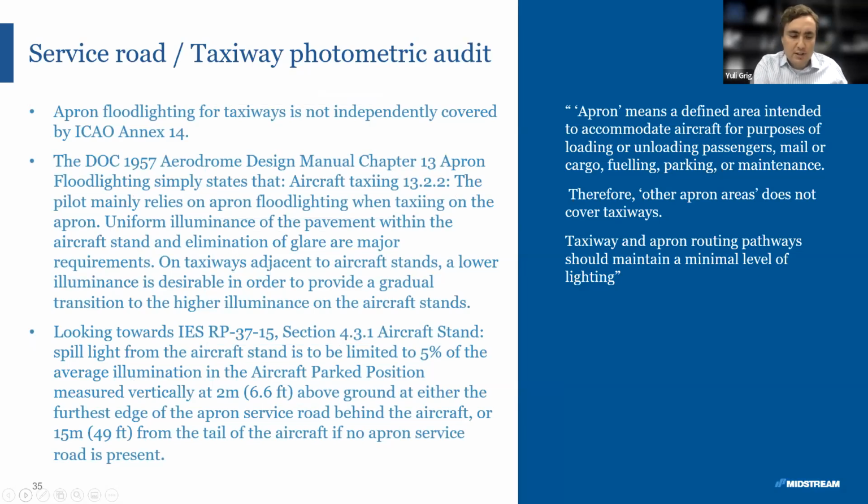We get a lot of questions about the service roads. They are part of the apron, therefore they need to have 50% of the light level. Well, that's incorrect, actually. Apron flood lighting for taxiways is not covered by ICAO. So taxiways are not inside the regulation or inside the recommendation.